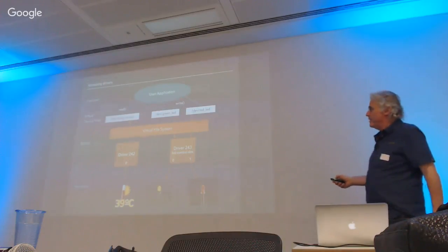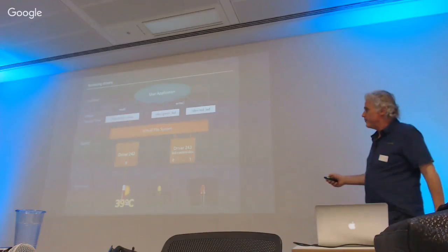And for example, this device file here called green LED, we can link that to this major number 243, so it's connected to this device driver here, and then in turn link that to 0 for this LED here. So this file here will be linked to 243 and then the minor number of 0.